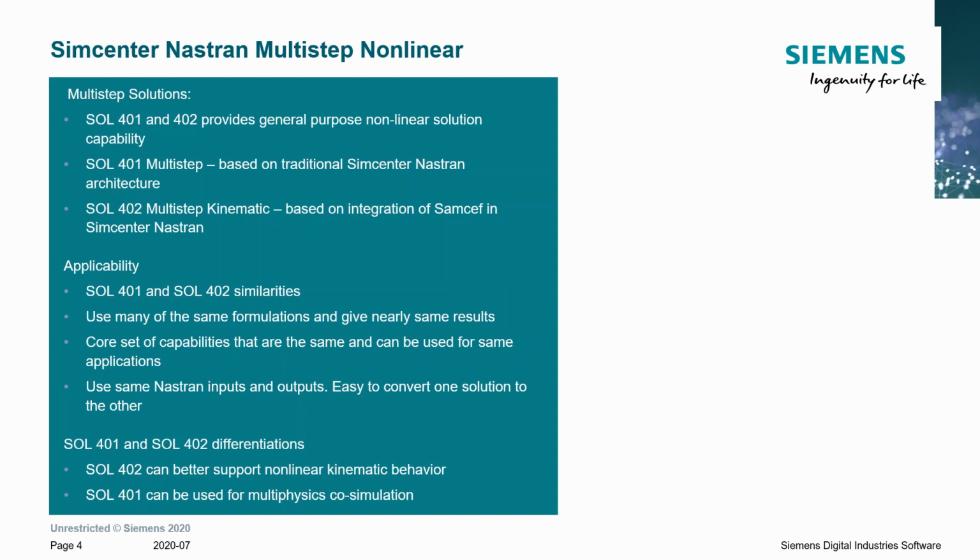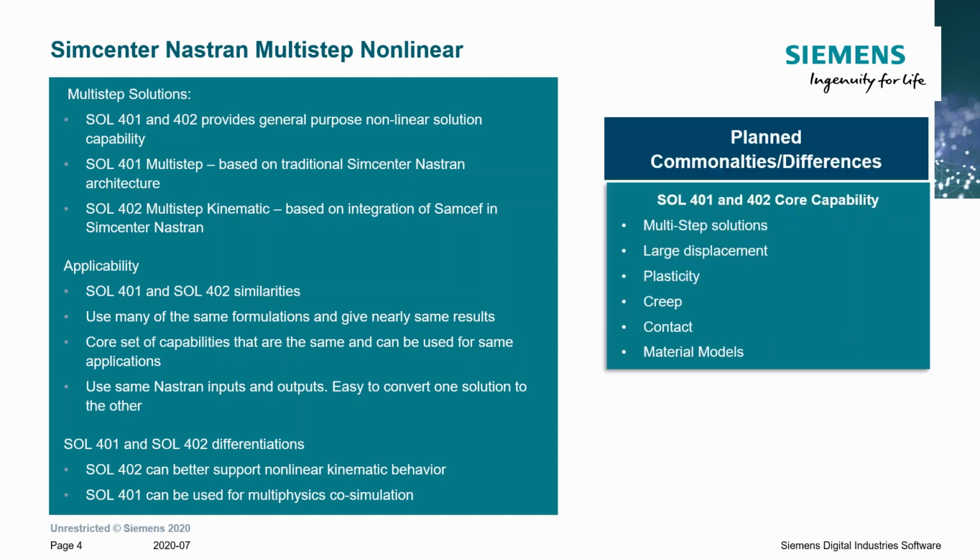Again, 402 has better support for nonlinear kinematic behavior. For example, any very large displacement or rotation applications. I don't know if people remember, at one point we posted an example of advanced nonlinear showing just a simple metal forming application. That would be a better application for solution 402 because you're getting into large deformation and strains and displacement. And solution 401 is used for multi-physics co-simulation.